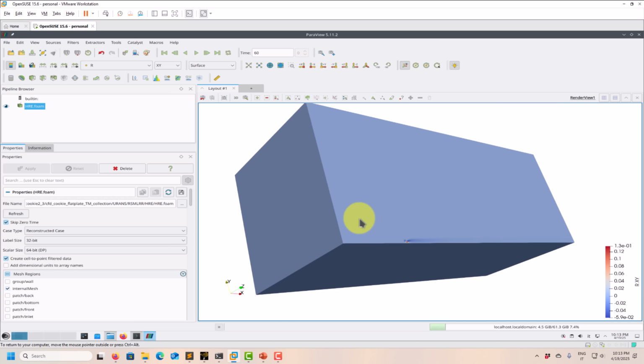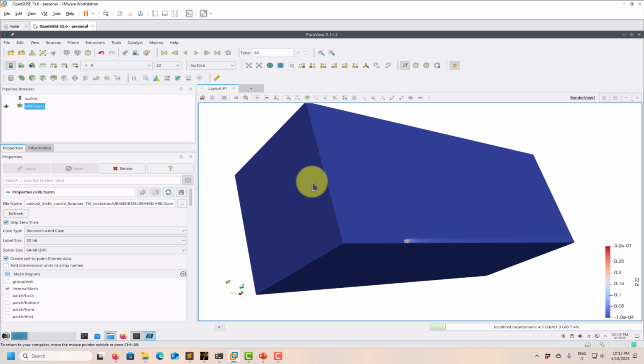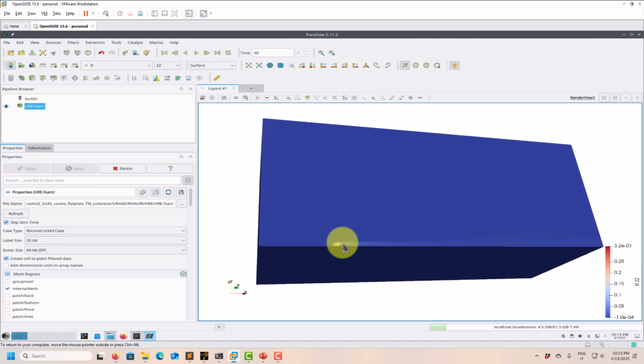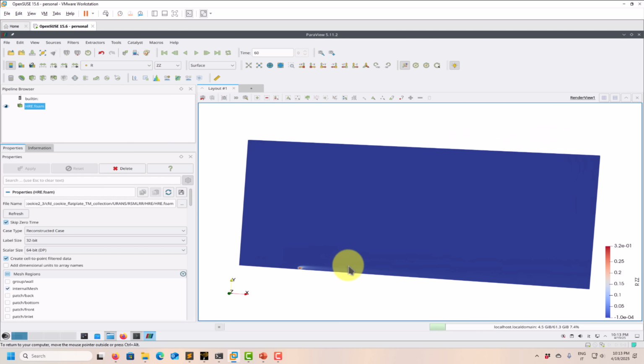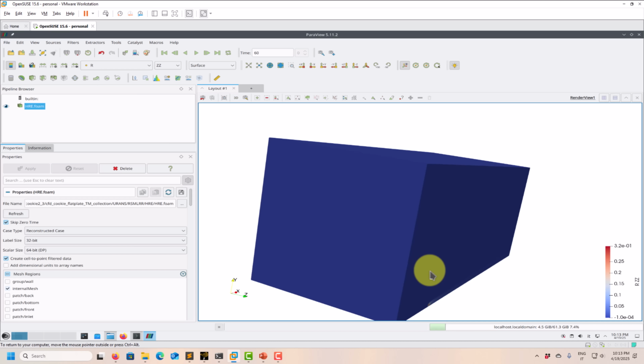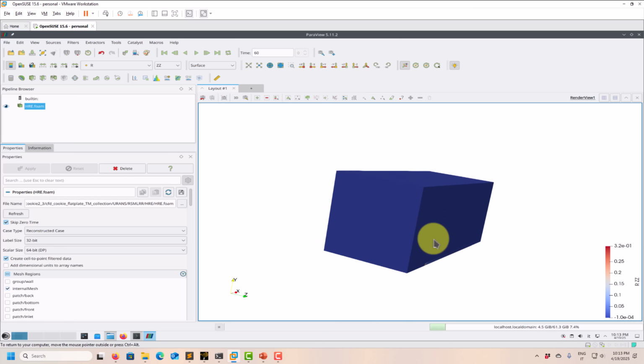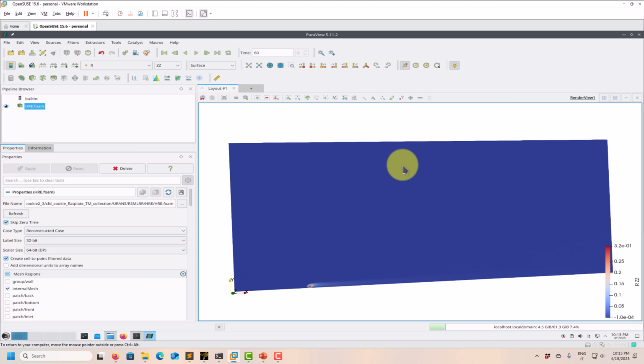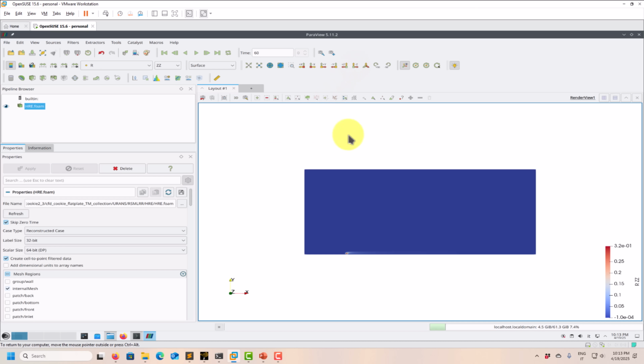And this is part of the reason why this case crashes: you have this component where now you're getting something there. So you need to add some kind of force in there to avoid that, and it will work. But many times it crashes in 2D cases because of this behavior. It doesn't mean that in 3D it will run. In 3D they also crash, and they're very, very difficult to make converge. So this is just to take a look at that.